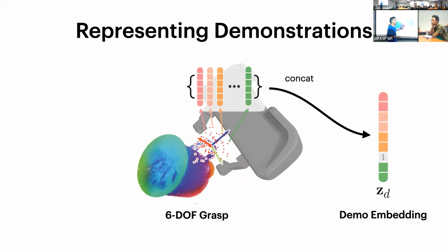But the robot doesn't necessarily know that. So in this case, we're helping the robot a little bit by saying that, okay, for this particular task, let's sample a very large blob around this area. And then we're going to either optimize the location of these points, or I can just tune the parameter of the Gaussian a little bit so that it overlaps with the part of the object that I'm interested in. So this involves our human priors.